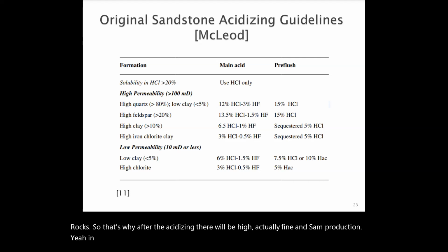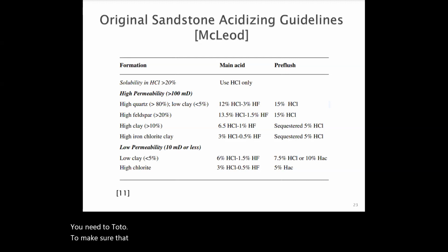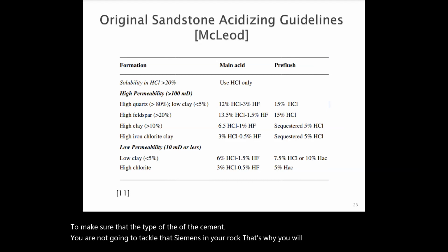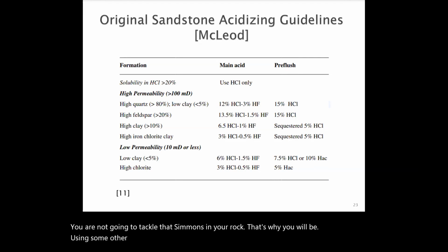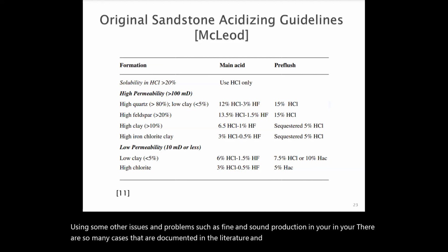You need to make sure of the type of the cements, so that you are not attacking the cements in your rock. Otherwise you will be inducing other issues and problems such as fines and sand production in your well. There are many cases documented in the literature and papers about this topic.